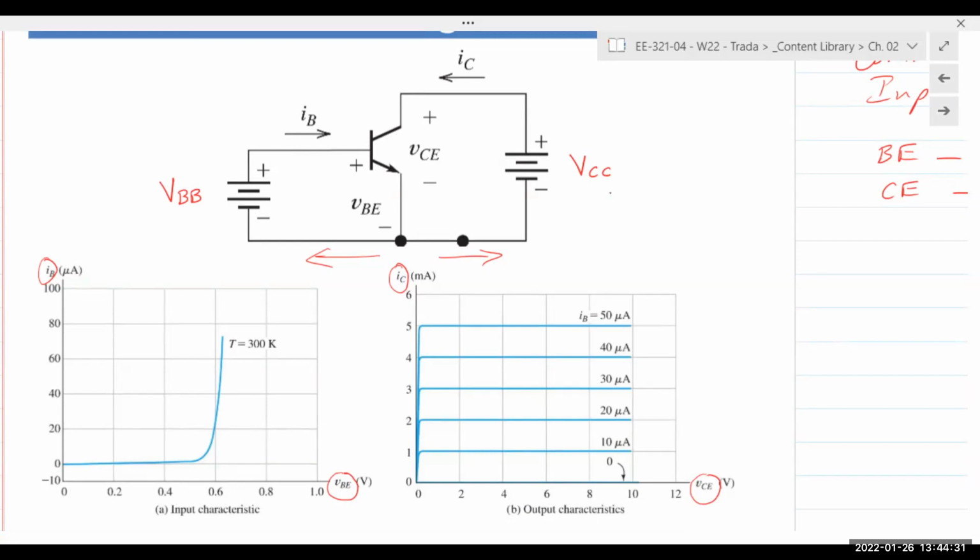VCE depends on whether the transistor is in cutoff or in saturation. Since we're taking the output here, if it's in saturation, maximum current is flowing, then the voltage is not going to be high. In the active mode, it depends on what input we give, so VC would fluctuate depending on the AC signal.